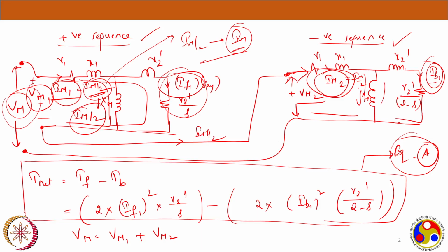We had derived only the torque equation at that point, which you are seeing. It's the two phase torque equation having two fields, forward field and backward field. We arrived at this using the sequence components derivations. This week we completed the discussion of how exactly a single phase induction machine equivalent circuit would look like, having zero starting torque and non-zero running torque. So this closed the discussion of last week.